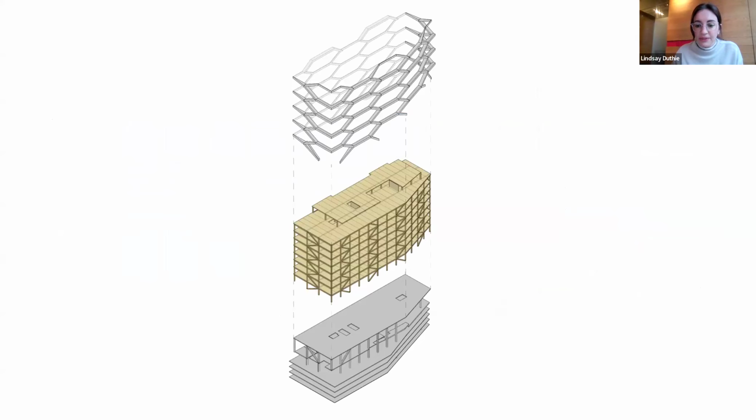So pulling this apart, the building consists of 4 levels of underground parking. We have a concrete first story. We have a tall floor to floor on the first level at 6 meters. And because of that slope I mentioned, concrete just really made sense here. And then above that, we have 9 stories of our mass timber structure. And then finally, the honeycomb exterior expression through the balconies.